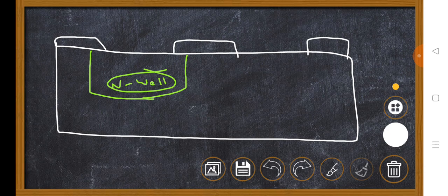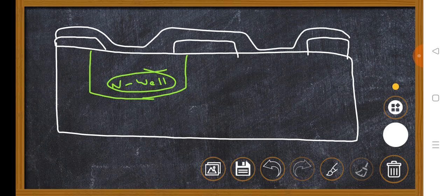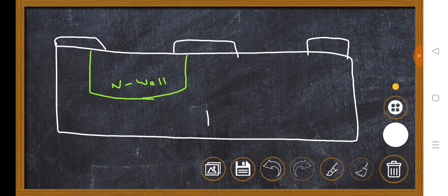After growing a thin oxide, you should perform photolithography and etching, where the thin oxide should be available at this position and at this position. Why? Because don't forget, you require two MOS transistors in a single substrate. I hope you are clear. And observe that after growing a thin oxide, after photolithography and etching, we require a thin oxide at this position and at this position. Is it clear? Then after that, what is the next step?